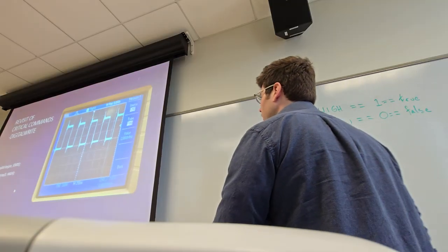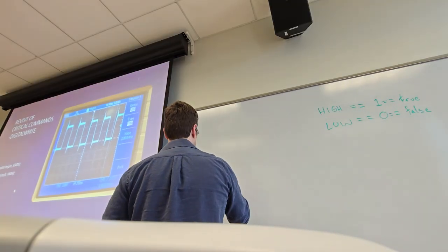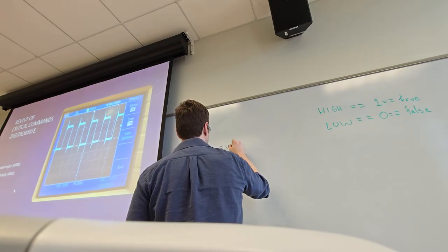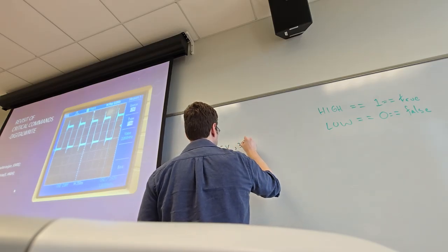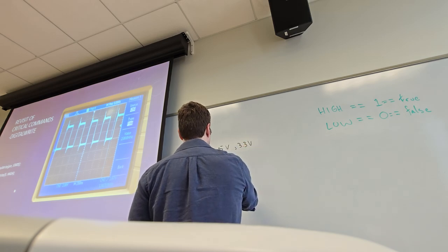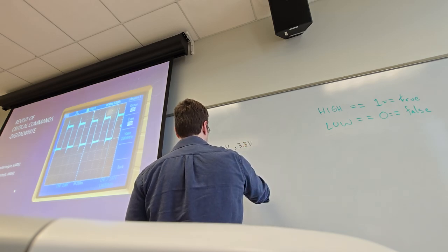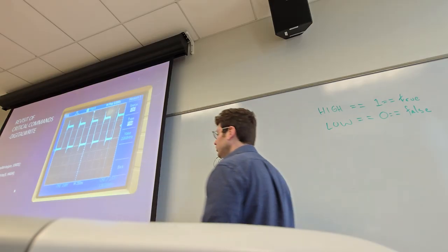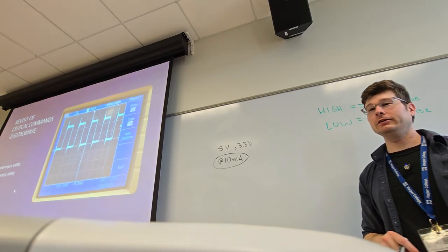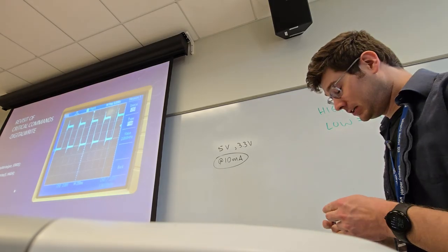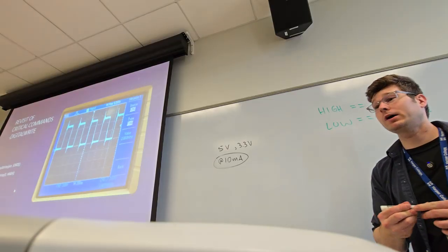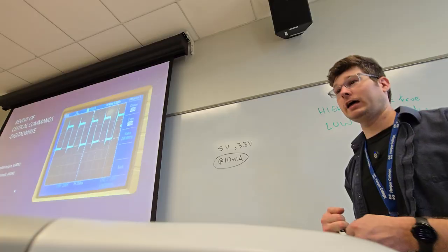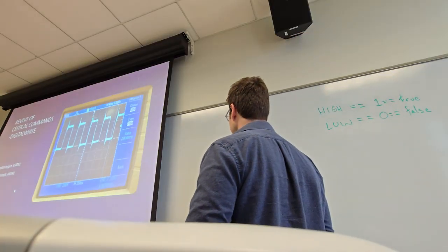I/O pins can source a small amount of current. Fun fact: they can give 5 volts typically for an Arduino, or 3.3 volts. But then they can also output about 10 milliamps on that pin. It's just enough power to drive an LED. It's actually why it's best practice to put a resistor on LEDs. You can drive them raw, but technically it takes all the power that the pin can source, which is not the best practice.